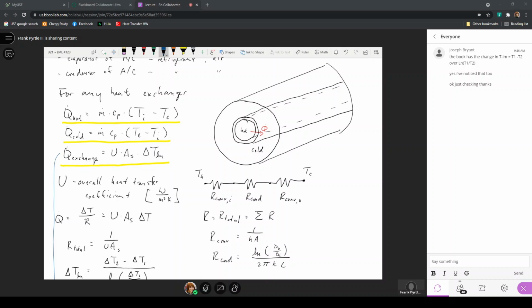coefficient, so that if I have additional conduction resistances due to oxidation, it will reduce the overall heat transfer coefficient that exists to represent what would be 5 resistances at that point if I added 2 more resistances due to conduction because of the oxidation.